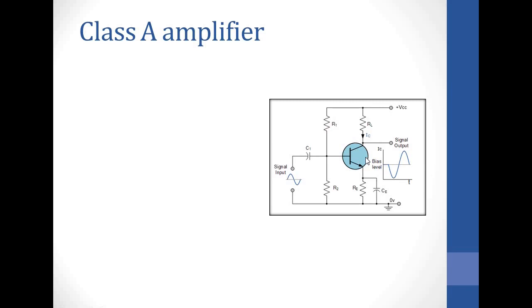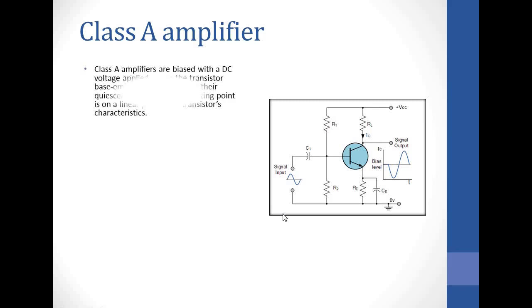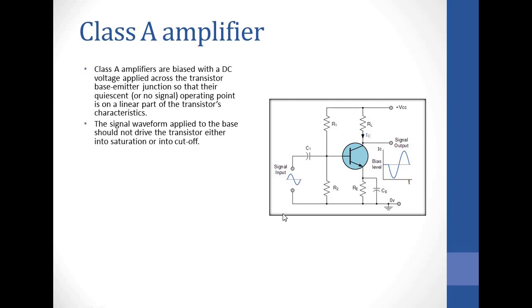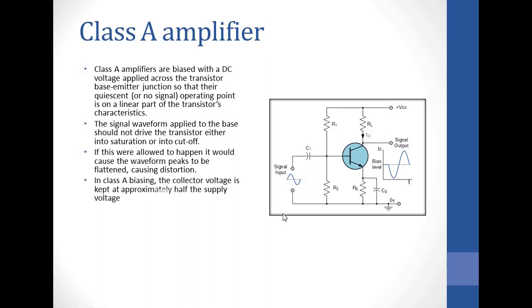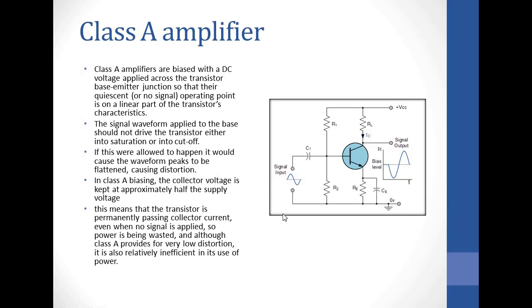So because of that, the transistor loses a lot of power through heat, and hence it has a very high power loss. And because of that power loss, the efficiency of this class A amplifier is very poor. So you can read on that. It operates in the active region, obviously, for 360 degrees, and the efficiency is normally between 25 to 30%.